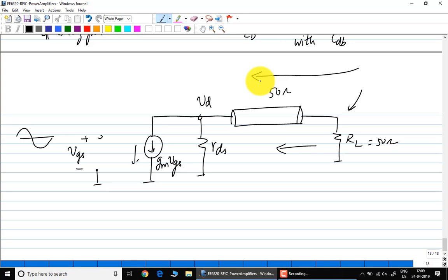Okay, so if you match the circuit, all these things will be damped. Does it make sense? So in general, because you are now designing the circuit to operate at the absolute maximum voltage possible at the edge of breakdown, etc., any additional swings you do not want to tolerate at the drain of the device. Okay?